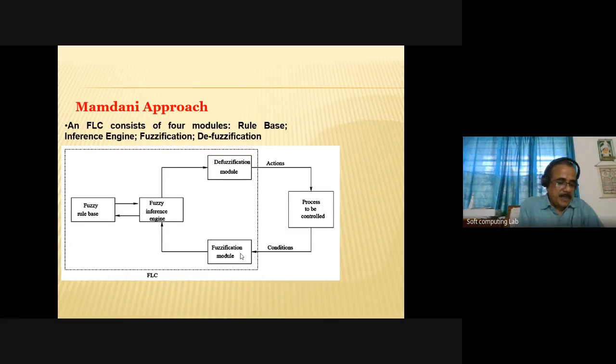Okay. Now, the first right angle triangle, if I write down, this is very low temperature. Then the first isosceles counting from the left side will be low temperature isosceles triangle. Then the second isosceles triangle will be your high temperature, and the last right angle triangle will be very high temperature. Can you see that? So you'll be getting some membership function distribution. Similarly, for all the inputs and all the output parameters, you'll be getting the membership function distribution.